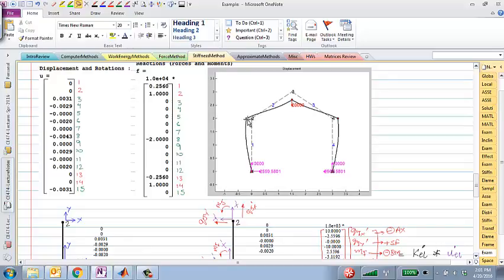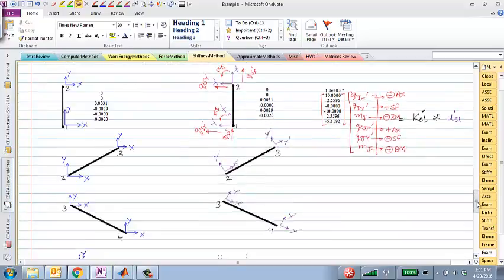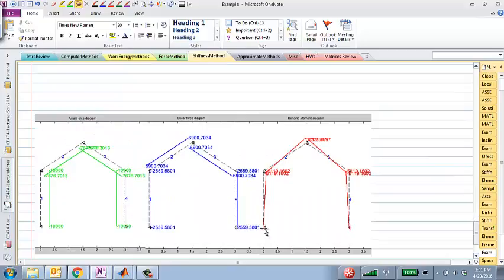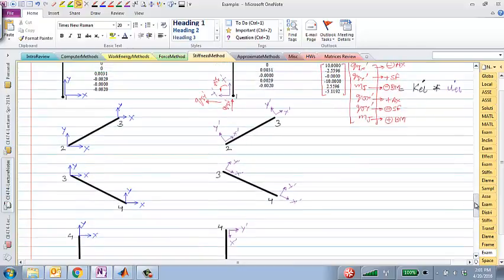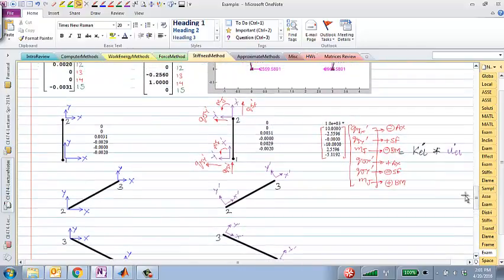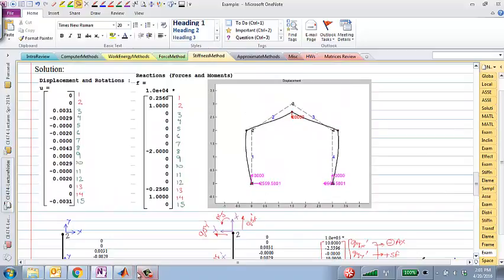If you look at the deformed shape, it kind of looks like that. And yes, at this point, the moment would be clockwise pointing into the plane, which would be a negative bending moment, right? So indeed, if you look at the bending moment diagram, it starts out at 0 and it goes to negative 5.119 kilo or kip feet, or kip inches is probably what I used here. So that's the calculation for the shear force, axial force, and bending moment diagrams, which is done automatically by the code that you have.